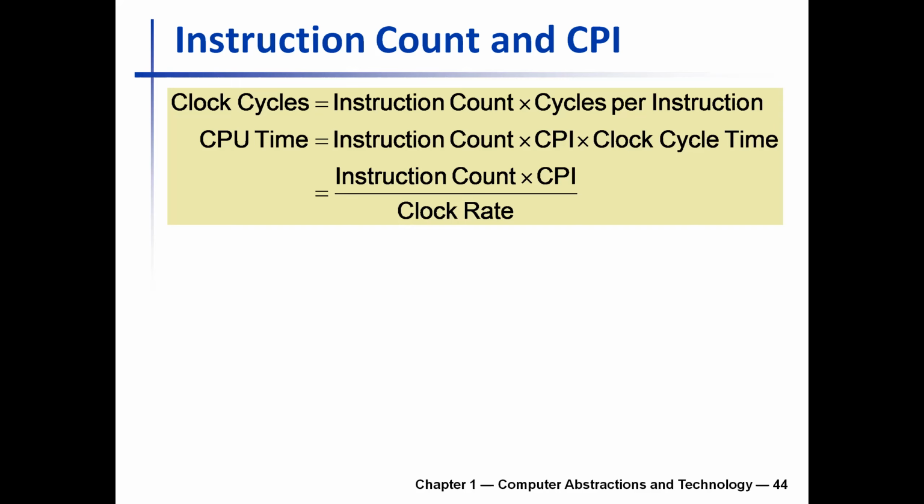In a single cycle processor, an instruction completes its entire execution within a single clock cycle. So an instruction is brought into the CPU, it's decoded, the register values are retrieved, the operations are performed, adding or multiplying or whatever, and registers and memory are updated. Everything you need to do for an instruction is done between two rising edges. That is the definition of a single cycle processor.